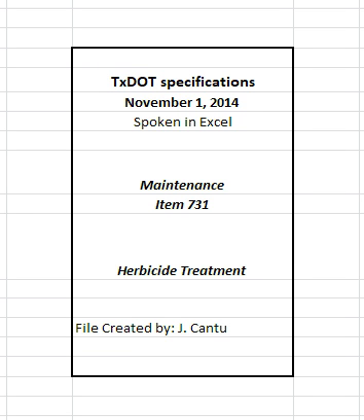7.2.1 Pavement. Spray a band of herbicide on and along the outside edge of pavement surfaces and curbs wide enough to spray vegetation growing in the pavement or curbs and approximately 6 inches of vegetation off the pavement edge or behind the curb. Do not treat roadways adjacent to highly maintained or manicured landscapes, such as residential yards or parks, with herbicides.